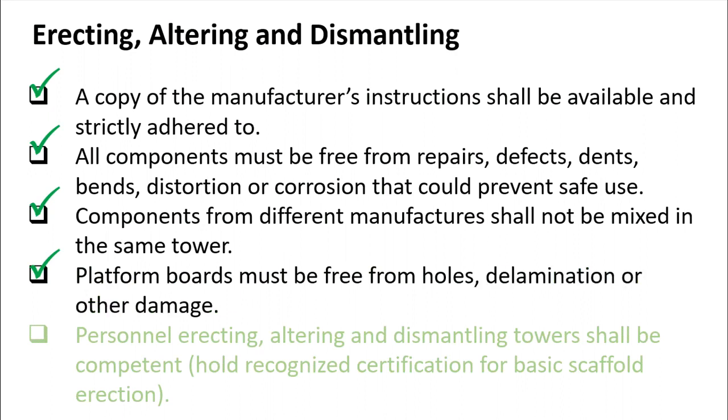Platform boards must be free from holes, delamination, or other damage. So make sure that all the platforms are in good working condition, so that it will prevent people from falling, or objects from falling through the holes accidentally.